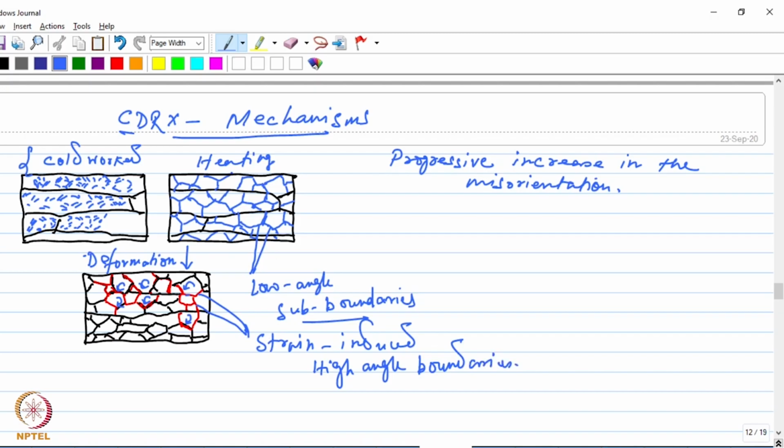And now these grains that you have generated due to this process, the grains which are bounded by these high angle boundaries, will be those new strain free grains, right? Because now the dislocations have taken part in a process like this, joining the grain boundaries and increasing the misorientation across them. And therefore the grain interiors will be free of dislocations and the material will be recrystallized.